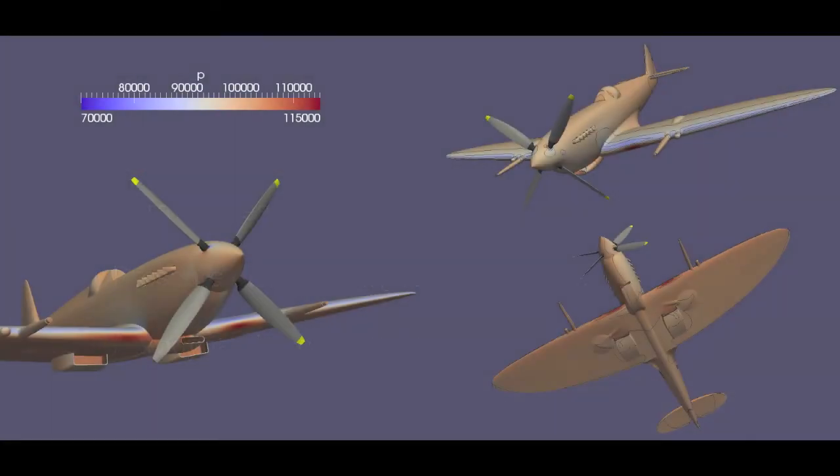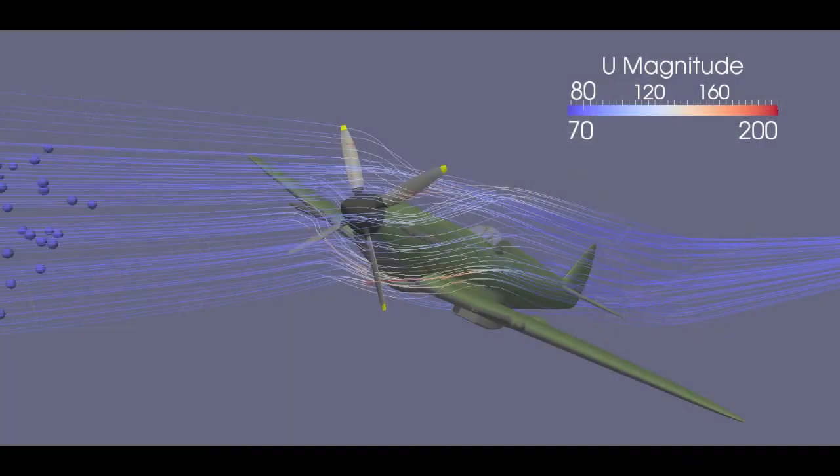Here you can see the pressure fields. Results seem to be reasonable: lower pressure on top of the wing and higher pressure on the bottom. Also notice that the high pressure areas near the leading edge are not in the same span-wise locations, since the propeller curves the airflow. And here is the flow field around the propeller. This is the average situation calculated with the moving reference frame.